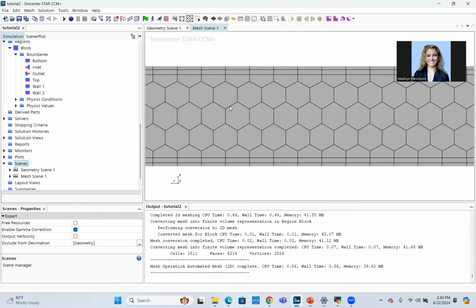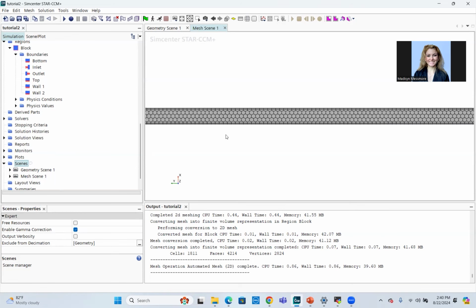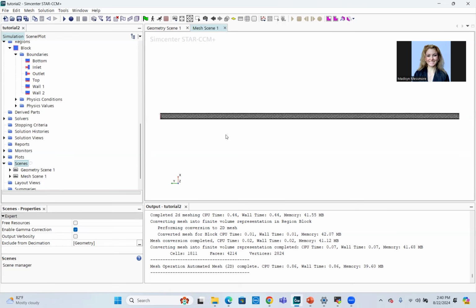We have broken down that big old geometry and put it into 2D, because it should be symmetric and we only really care about this plane. And we've broken it into these cute little chunks. They should be 5 millimeters-ish, which is effectively the maximum size of these chunks. It should be uniform-ish throughout our geometry because our geometry is fairly simple.